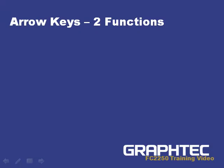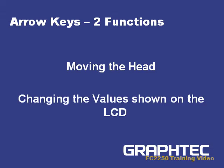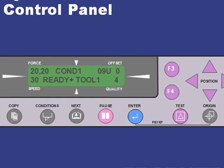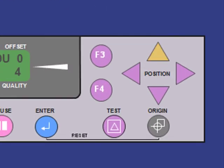As mentioned, the arrow keys have two functions. First, moving the head, and then second, changing the values on the LCD menu option when it calls for you to change the value. Let me show you how moving the head works when using the arrow keys. When the plotter is in the ready mode, by pressing and holding down any of the arrow keys, up, down, right, or left, it will move the tool head in that direction. By releasing that arrow key button, it will stop the movement. This will enable you to position the tool head to a desired spot or position.